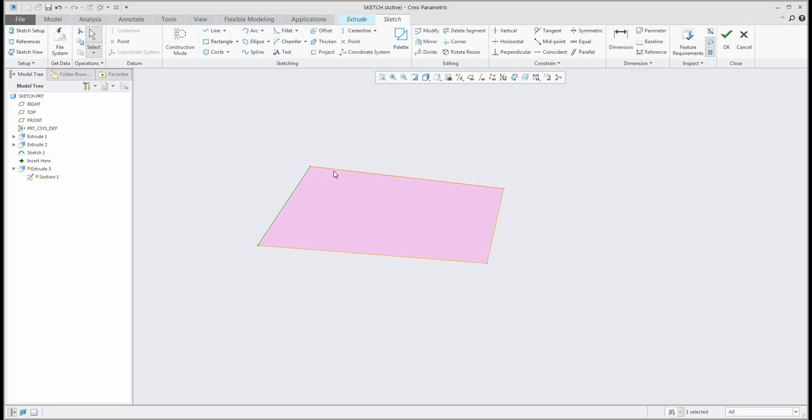And then you can use the function create a constraint, and it's up to you which constraints you use. You can use it directly on the selected objects, or you can use the button from the ribbon. So I would like to use, for example, perpendicular between two, and parallel is not necessary. I'd like to use the equal. Yeah, perfect. What is necessary to do? We can select horizontal, and that will be horizontal. So you can see here how it's possible to create a closed shape from one line.